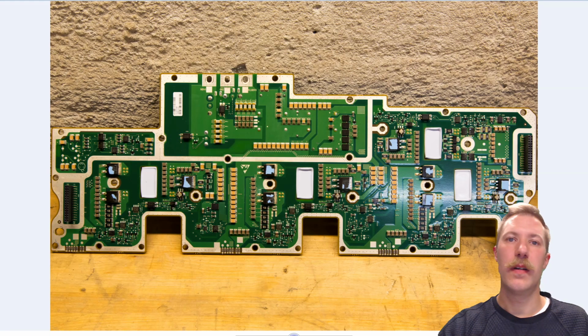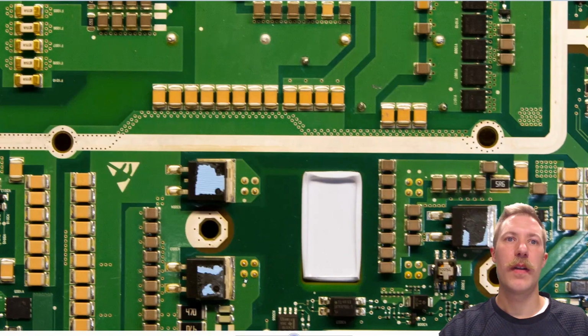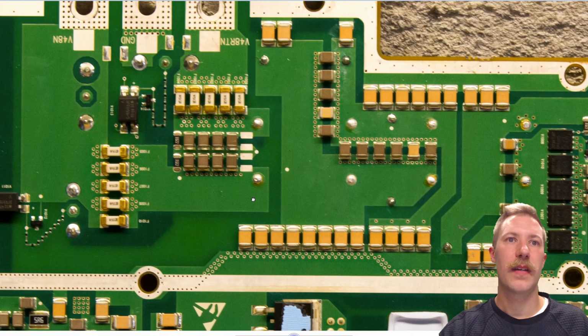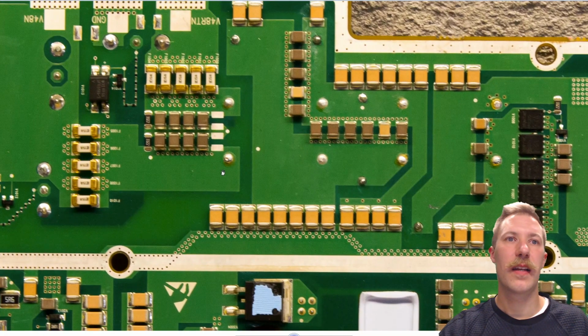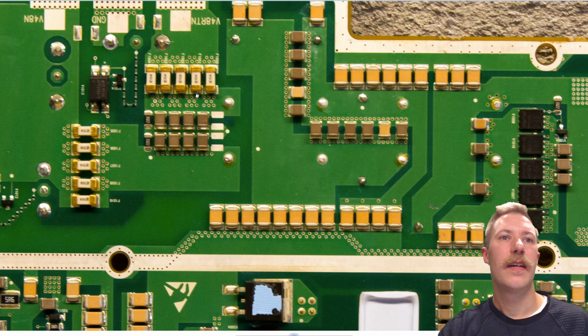Now a few details about the power supply is that up here, I'm sorry for the little blurred image here, but there's actually these gold-plated small components here are fuses, and having 10 of those in parallel, 5 per rail, is actually how this unit is fused on the input side.